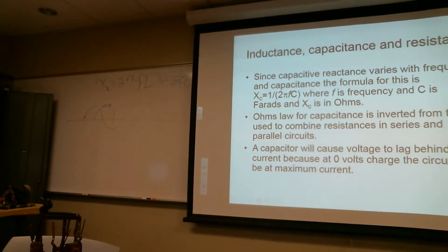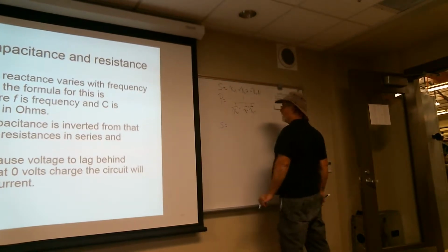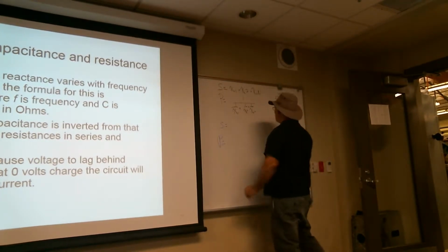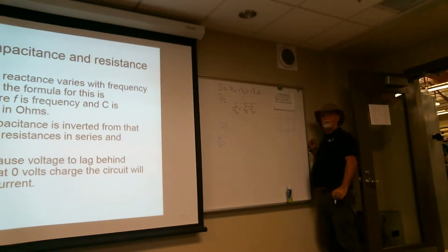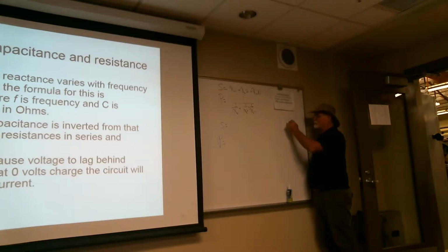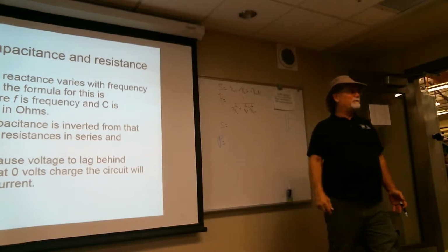Okay? The other thing that we've got to look at is when we hook them up in series and parallel. Well, let's do parallel first. In parallel, when I take two capacitors and put them in parallel, like this, what have I done? Can't I just go like this and say I made the plates a little bit bigger? I just increased the size of the parking lot by that much. So all I have to do is add them together.